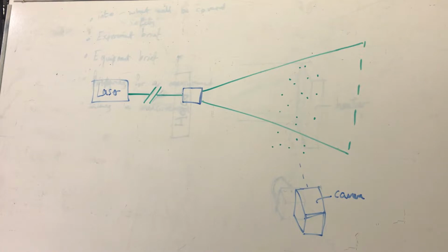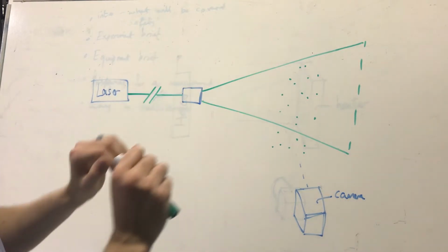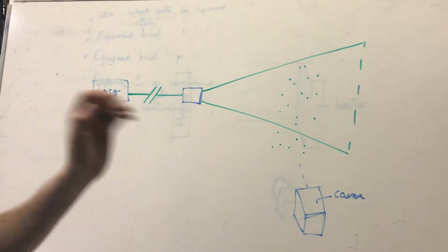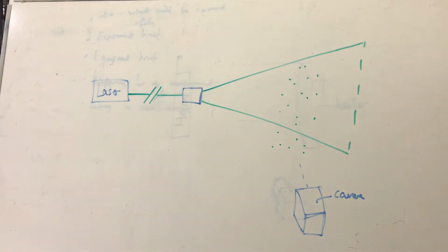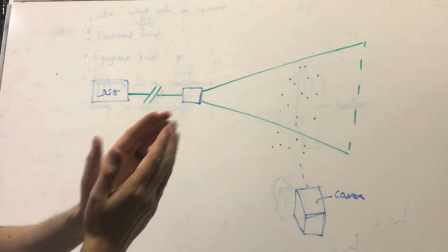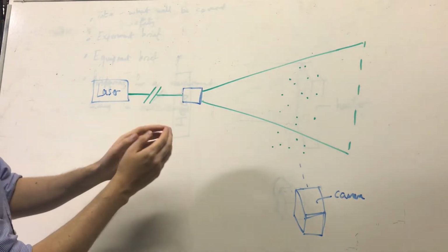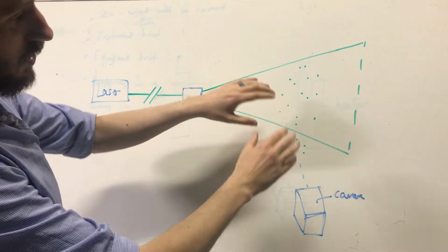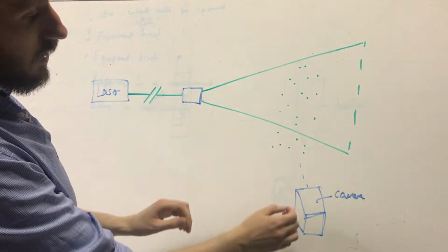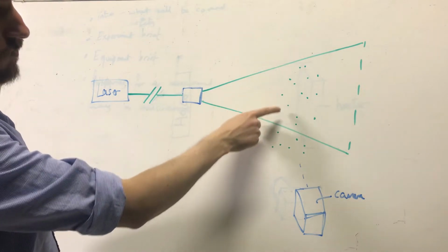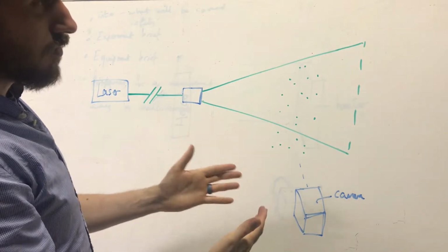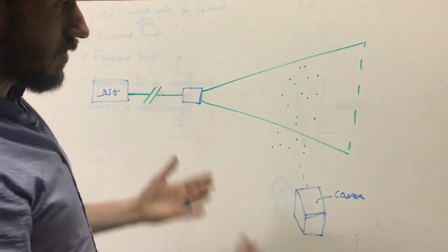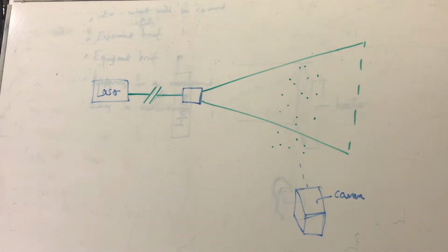It operates in a pulsed arrangement, which means it kind of goes pop, pop, and you typically have 2 pulses, and with each of those pulses you simultaneously gather an image with the camera. And so what that means is, if you know strictly when those pulses are occurring in time, or the difference in time between one to the next, you'll have 2 images of where these particles are, and you can use the apparent displacement of the particle images and the known difference in time between those images to infer the velocity of the flow. So it's a relatively straightforward thing. Just a change in distance, a known difference in time will give you velocity.